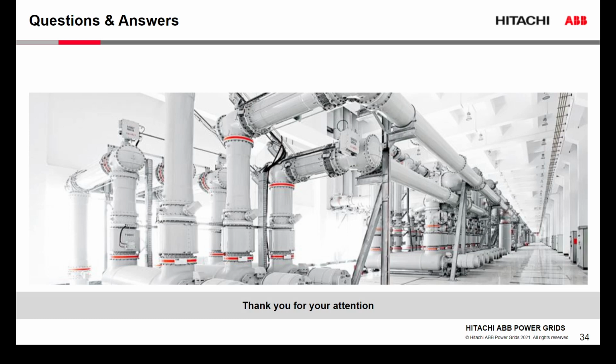Okay, Thomas. Our next question is, what is your recommendation for deciding between an indoor versus outdoor GIS? I would usually all the time say go indoor, because you would not repair your car on the street, but usually deciding factors are temperatures. If the temperature goes below -30°C, typical breakers, and that is also true for conventional breakers,